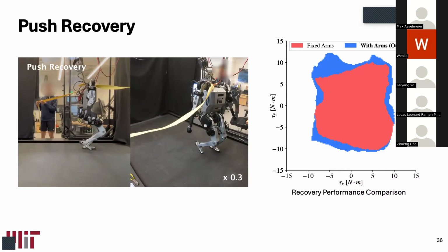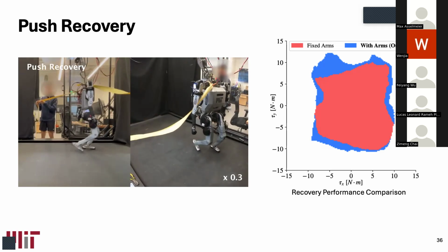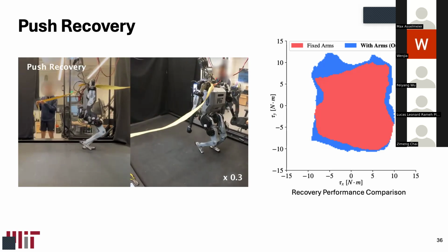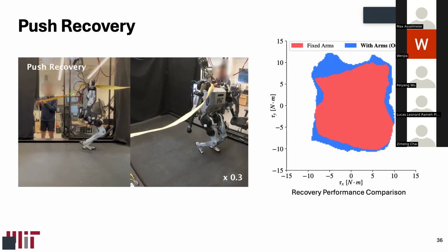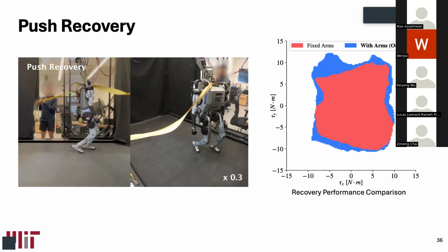Sometimes during RL training, even if we use motion reference guidance, we still find the left leg and right leg are not perfectly symmetrical. Similarly, for the arm motion in the left perturbation case, the right perturbation did not train perfectly, because during training we use domain randomization and push it, and that might not be exactly five times left perturbation and five times right perturbation. So that's how it converged.